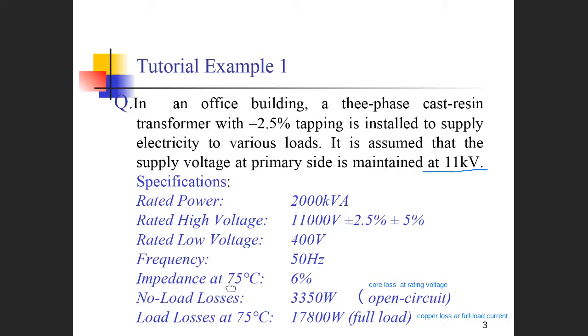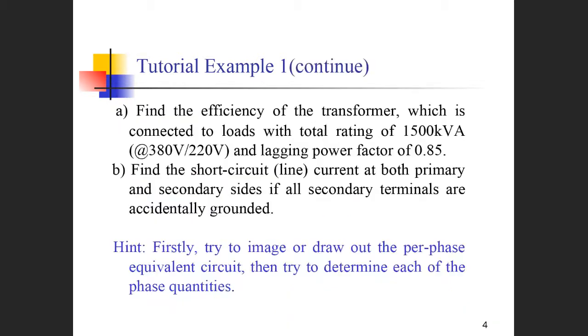This is because the resistance changes with temperature. So here the main thing is the resistance. The reactance changes with the frequency, but here the frequency is given. So these are the specifications. Based on these, we can get several internal parameters of the transformer by doing simple calculations.